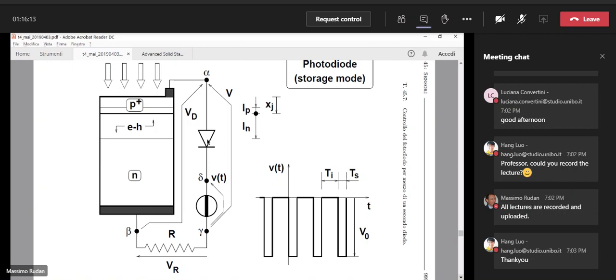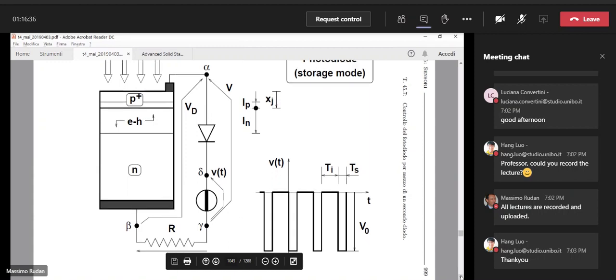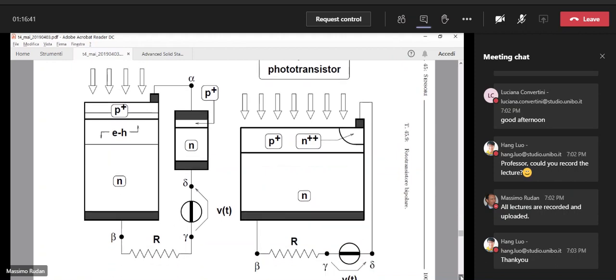Okay. You simply may imagine that you seize the switch diode and drag it upwards and then to the left and push it into the photodiode. Okay. What do you get? Well, obviously, what you get is this. So on the left part, we still have the two devices separated, but the switch diode, instead of being drawn as a symbol, is drawn with the actual structure, okay? And then we bring its P region into, and we merge its P region into the other region, okay? So if you do this, what you obtain is the structure that is shown on the right side of this figure.